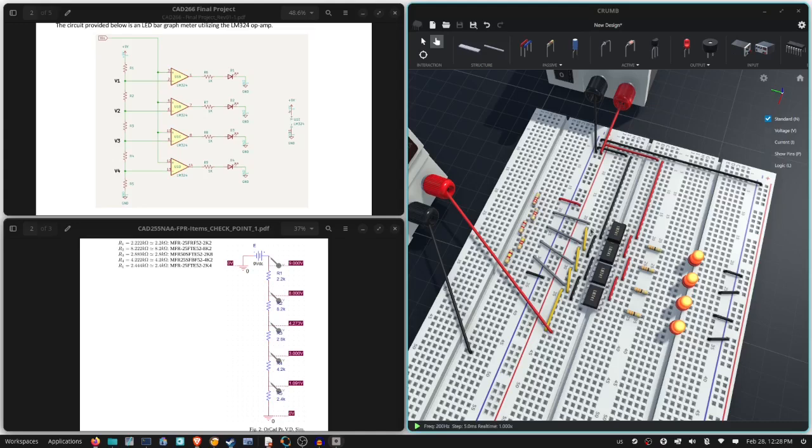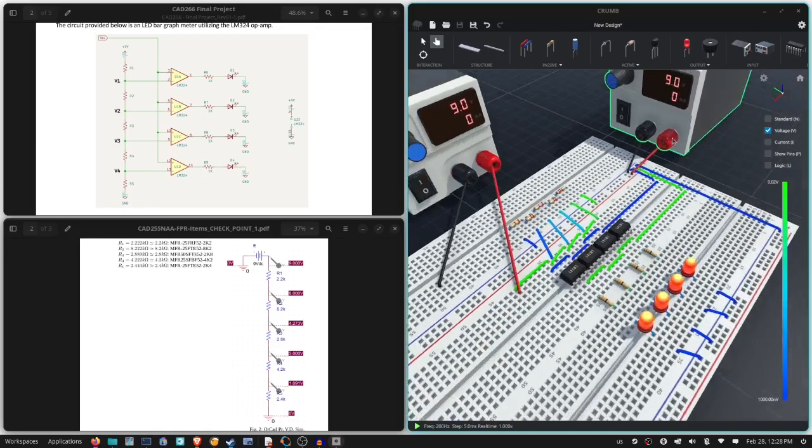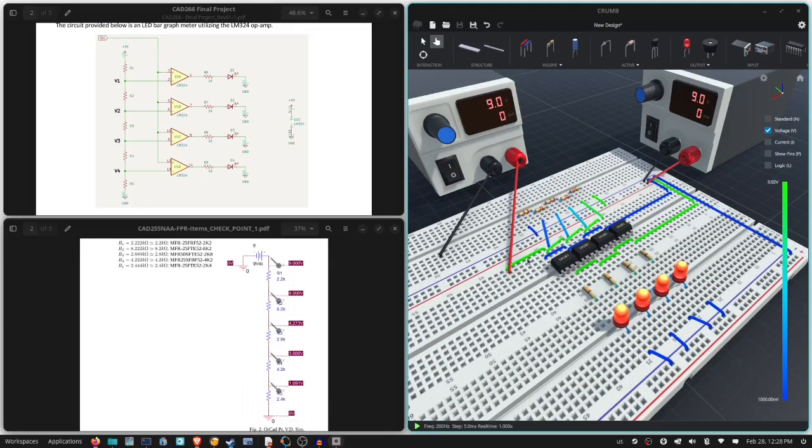So we're lowering the voltage. You can see in the voltage, we're lowering the voltage. It should be 8 volts here, 4.3 volts-ish here, and 3 volts here, and 1.1 volts here. Right? So we're going to slowly lower the voltage, and we're going to find that once we read around 8 volts, this first LED is going to shut off. You'll see this green voltage sort of go down. At around 8 volts, the first LED shuts off.